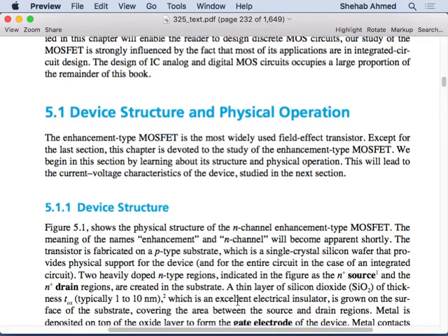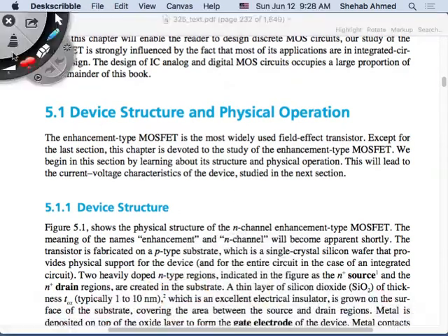And there are 2 types of MOSFET based on how you design the material, right? In the diode, we used P-type material and N-type material, and we created a PN junction, right? Same thing here with the MOSFET. We will still use N-type and P-type material. So this doping, all the stuff we talked about for a while when we talked about semiconductors, even though we didn't really take homework problems on it, is critical for understanding MOSFET and BJT operation. So drift and diffusion is very important.